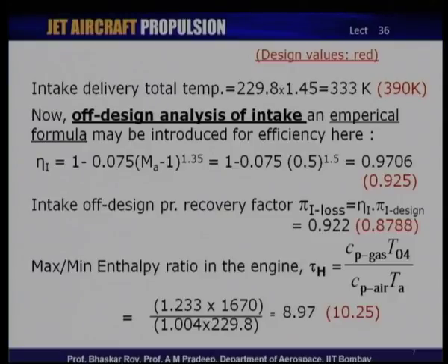From these calculations, we can say that the intake delivery total temperature would be 333 K, which is again far less than the design point value, which was 390 K. So, the flow was going into the compressor earlier at a somewhat higher temperature. The off design analysis of the intake uses certain empirical, or semi empirical, formula here to calculate the intake efficiency.